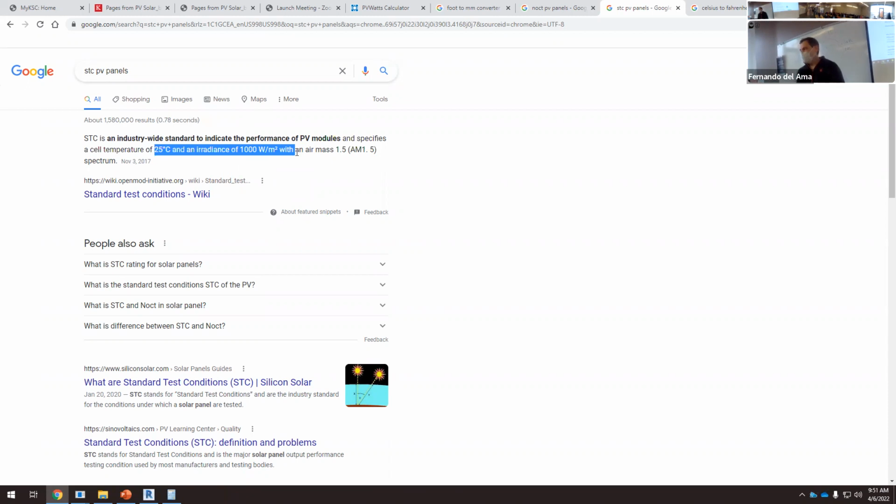So when we have this efficiency under standard test conditions, that means that we will be producing this for a few seconds a year, because it's very likely that when the temperature is the optimum temperature, we have a cloudy day, or when the solar radiation is the best one, the temperature is either too hot or too cold. So we are simulating something under ideal conditions, and the reality will be worse. You understand that?